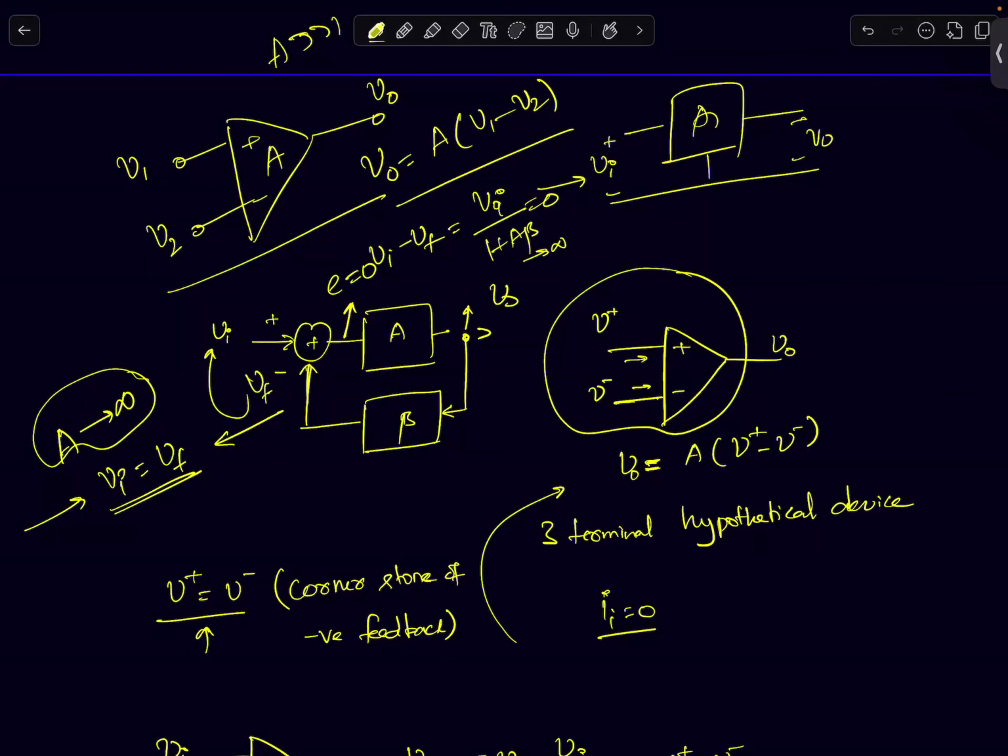Okay, so you can see that if you increase this node, this is just a constant beta, this node will increase, but there is a minus sign here. So when it comes here, this node will decrease. So this node will also decrease. I began by increasing this node, but the circuit responds by decreasing it. So now I know it's a negative feedback. So that's one way of testing it.